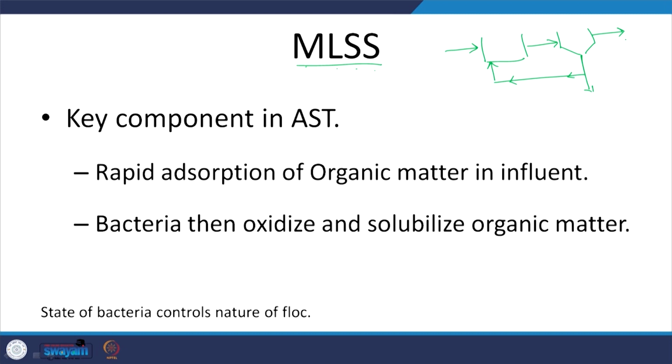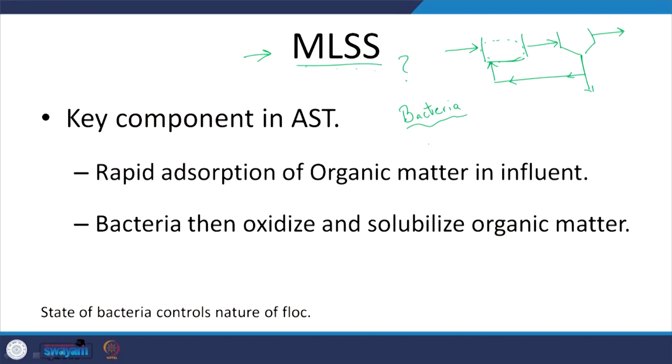And what do we have here? We know now that the concentration of microbes here is going to be pretty high. So, the contents of this aeration tank are called mixed liquor suspended solids. What does that contain? Obviously, it will contain bacteria, a lot of it, depending on how you are maintaining it. What else will it contain? The MLSS will also include some inert solids or fixed solids.